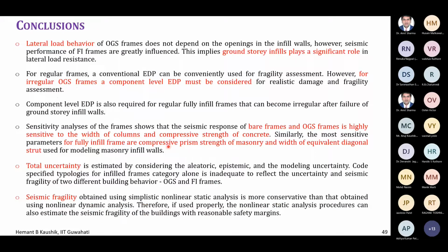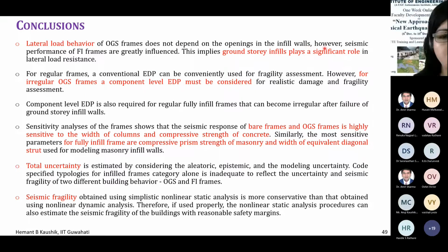So these are the final conclusions of the talk today. That the lateral load behavior of open ground story frame does not depend on the openings in the infill walls, right? But the fully infilled frames, they depend. So that means the ground story infill plays a significant role in the lateral load resistance.